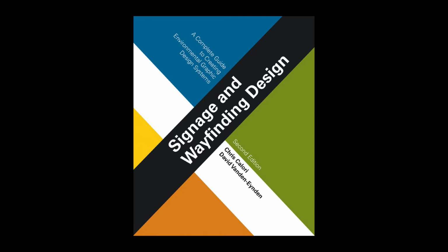Many of these shapes are used for general construction industry applications and are available in a variety of basic cross-section shapes, such as round, square, and rectangular tubing, as well as L-shaped angles, C-shaped channels, and the classic I-beam. There are also manufacturers of extruded aluminum support components with more varied sectional shapes geared specifically to signage applications.